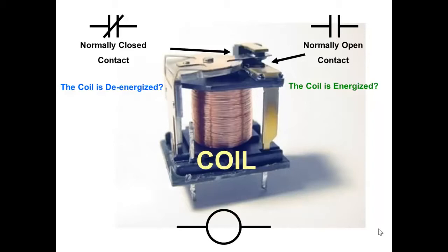In other words, you have a circuit that when the circuit completes, it energizes this coil. That circuit could be made up of many individual devices wired in series, meaning it could be three switches from three completely different locations in the process. They're wired in series, so all three of them have to be closed before the circuit is complete and energizes the coil.